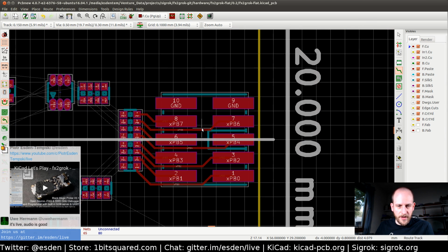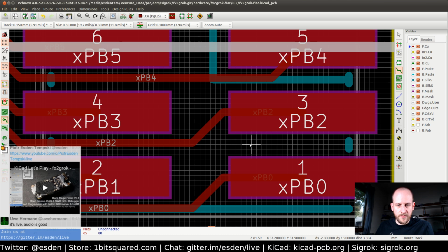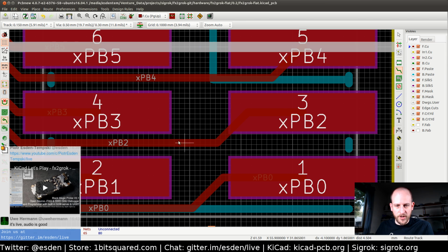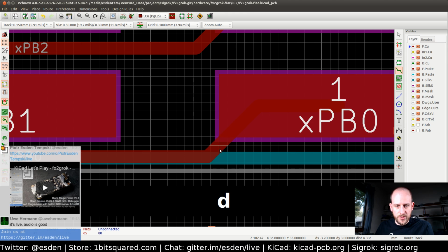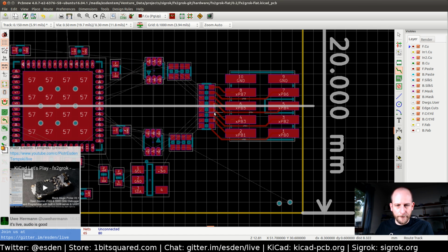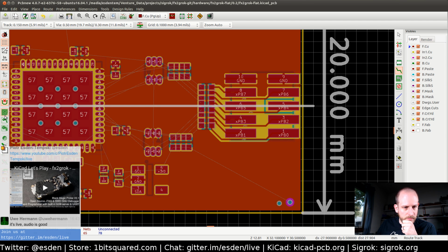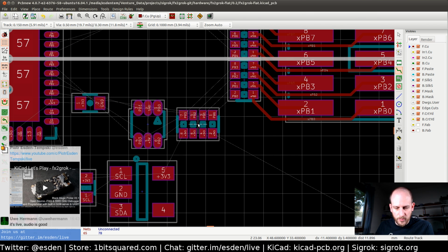Yeah, this is where you have a footprint with imperial spacing against a metric design. It's a little bit iffy. We can have this so that it is using 45 degree angles to escape from the pad. I like that better. And this guy too. Okay, cool. So these guys are connected. Bam.